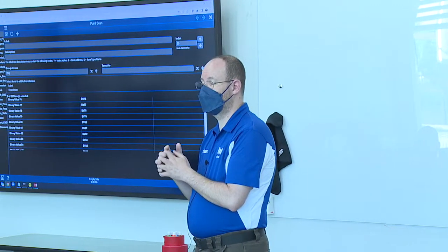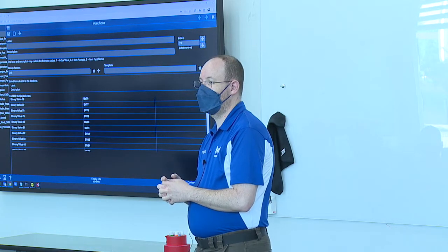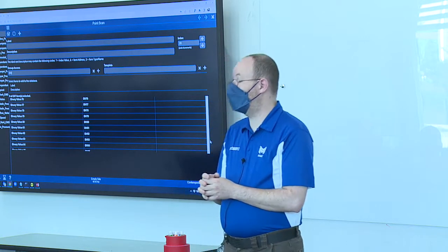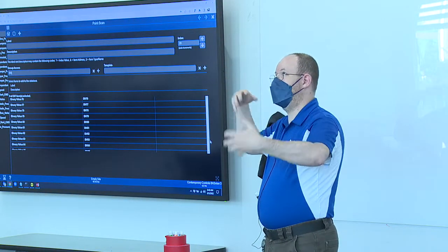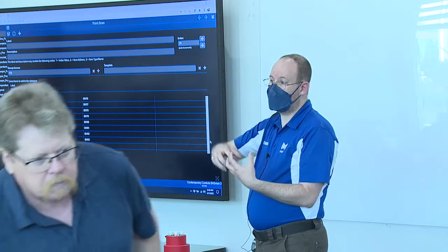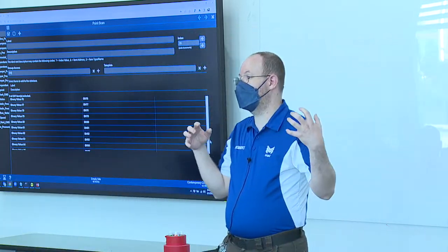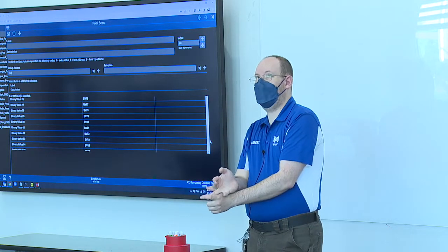There's one point on the scan, the device object. Is that one we want to add in? No, that is literally just the object point within the controller that contains data about the controller. So it will tell you the controller's name, manufacturer.